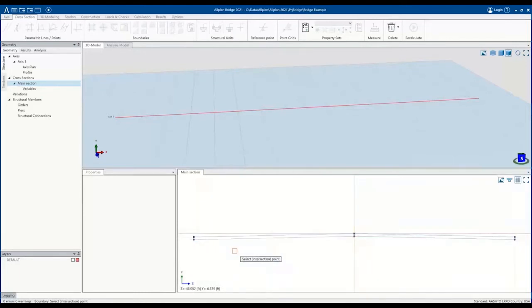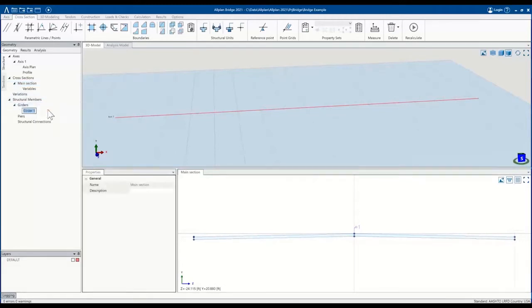So to name a simple example, if we wanted to have a splayed girder arrangement on one half of the bridge on one span, we could change those girders from being spaced uniformly at 6 or 8 feet on center to saying at one end we want these at 6 feet on center, at the other end we want them at 9 feet on center. Give us the necessary width to develop an on or off ramp.